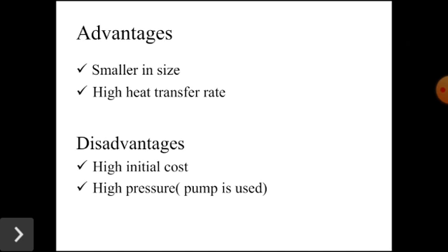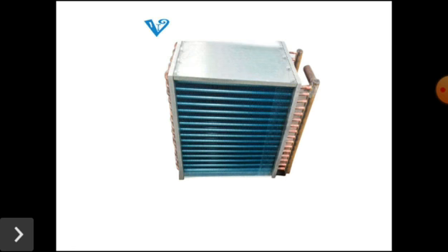Okay, I already said the advantages. One more advantage is that a high heat transfer rate will be there in this type of heat exchanger. Disadvantages: since it is compact in design, it requires a high initial cost. Here the fluids are pumped through a pump, hence there will be a more pressure drop. This is the compact heat exchanger general diagram.